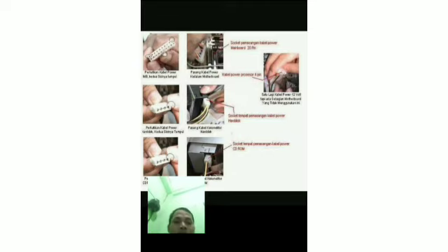And number 9. Install the ODD optical device drive such as DVD and HDD hard disk drive. After the power supply cables are attached to the mainboard, the next step is to install the drives in the casing. Adjust the drive according to the drive space in the casing. Usually, the DVD is placed in the top front bay of the casing, while the HDD has its own bay.